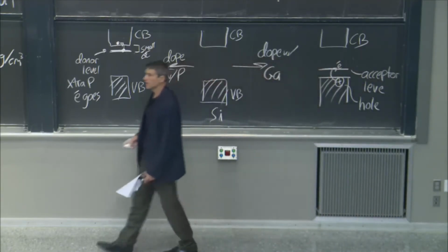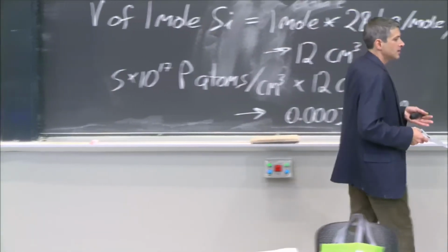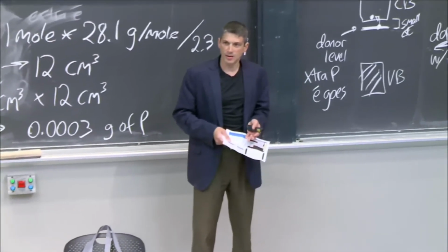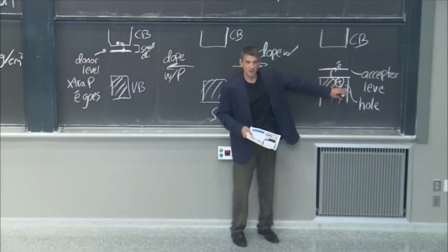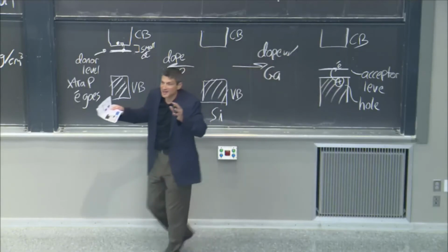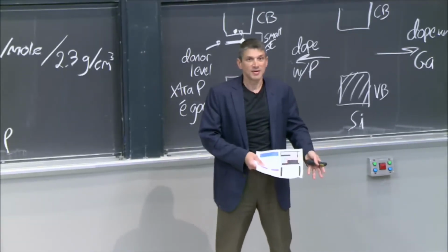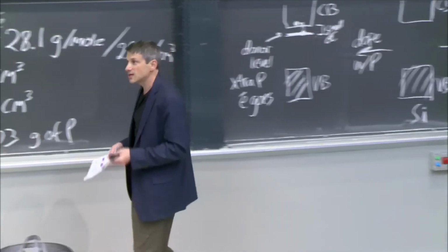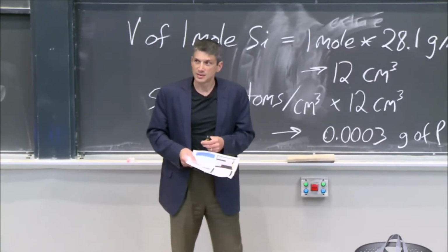That's called a hole. Think about it: if I take an electron off of an atom, it's positively charged. If I take an electron out of the VBM, there's a positive charge in there. That's really important because these positive charges effectively are like electrons. They're like negative charges, but they're positive. So they also can conduct, right?